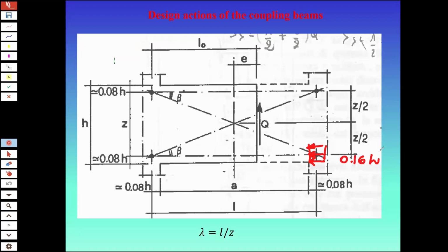Well, and then, okay, we understand why we have to go up, but why do we have to go inside? Well, because the flow of the stresses actually will be inclined like this. And so you can imagine that your strut, because we will use a strut and tie model, cannot be anchored at this corner point, but must be anchored into some kind of solid concrete region.